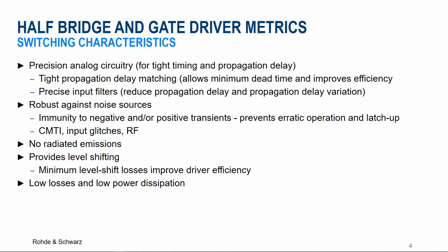Higher frequency can also lead to negative EMI conditions. A primary industry concern for silicon carbide adoption is if it can demonstrate that it is not excessively noisy compared to silicon, and the need to demonstrate that EMI is not a limiting factor. Thus, it's critical to contain and visualize the effects of high dV/dt and dI/dt. And in general, most labs don't have good solutions for testing these radiated emissions, so they simply don't test for it.